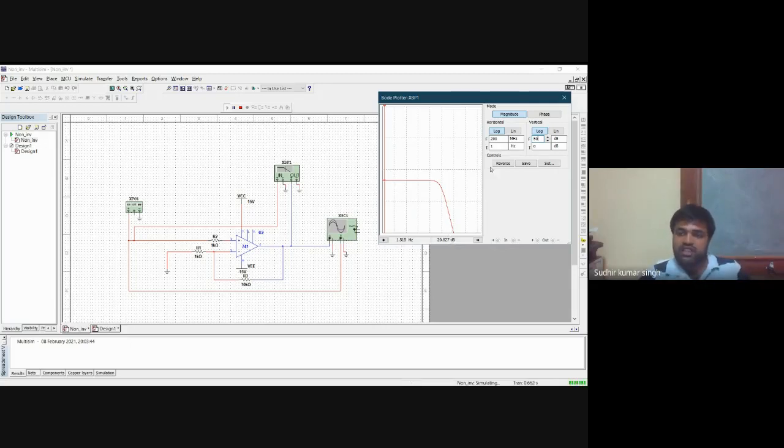Now, if you can see, I have made initial 0 dB and final 50 dB, meaning in a 50 dB scale I am seeing it. I can also make it customized. Let's suppose I keep 25 dB. So in 25 dB range, you can get a clear picture. So 20.8 is maximum, then 20.8 minus 3, so 17.6 or something, right?